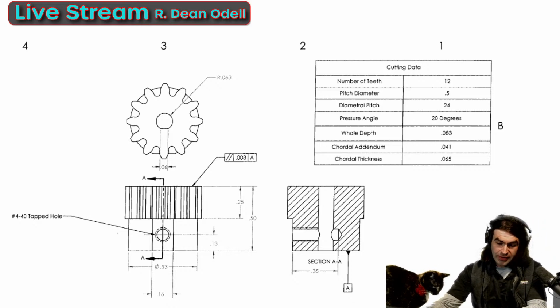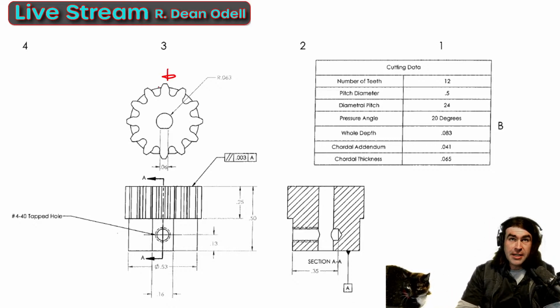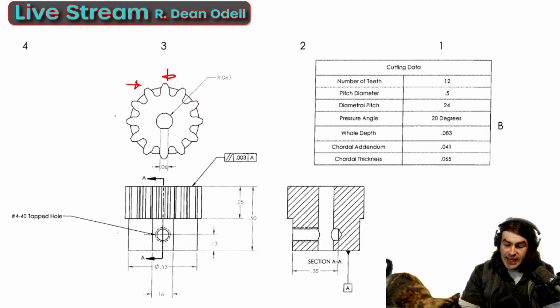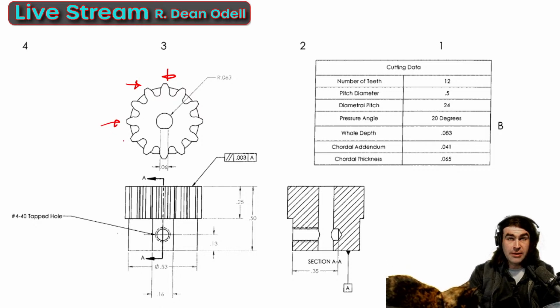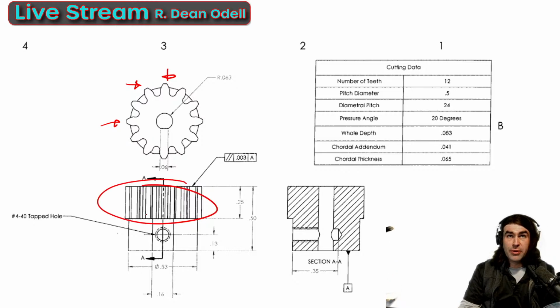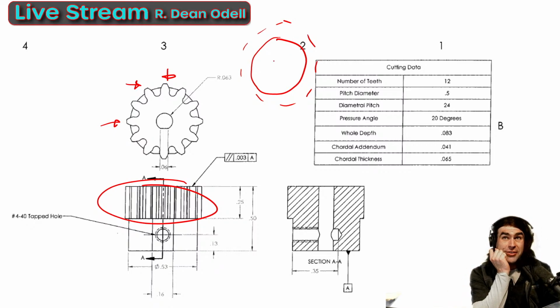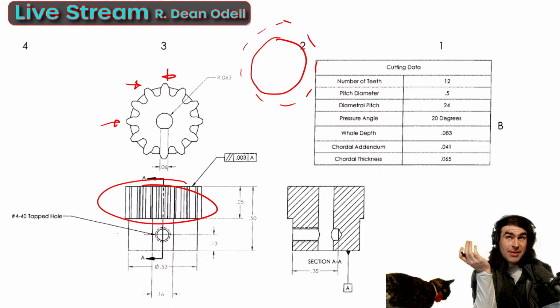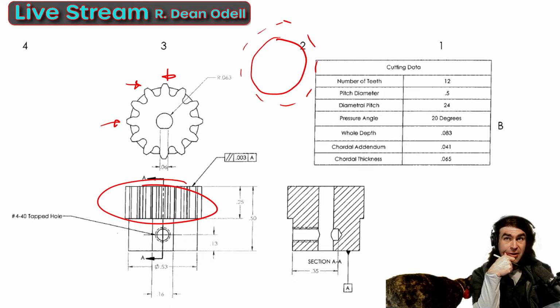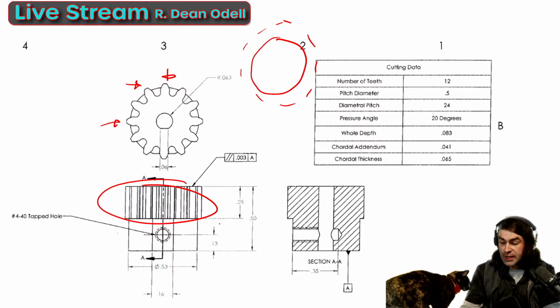started. This, as you could probably tell, is a gear, right? In modern CAD systems, you can leave gear teeth. It's fine. I'd almost not recommend it though, because it clutters up the drawing, in this view especially. What they used to do when you had gears was use a hidden line, like you would do on a thread, to indicate the minor and major diameters of the gear, and that way you clean up the drawing.